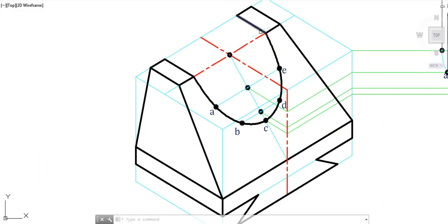Now as this particular curve is actually a curved surface which is continuously going inside, and at the end, since there is a flat vertical surface present starting from this point, this inclined curve will be shown there as a circle. So using the 4-arc method circle, I am going to draw a circle there, or the semicircle basically. So let me show you how to use the 4-arc method and draw it.